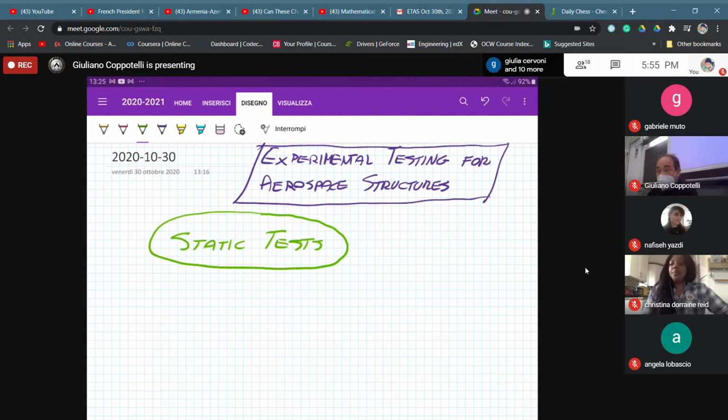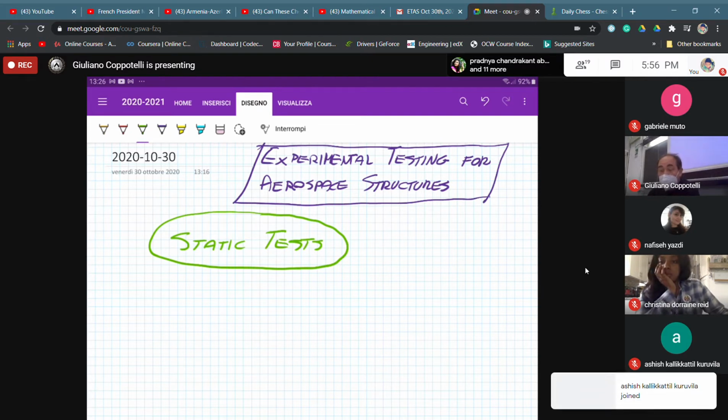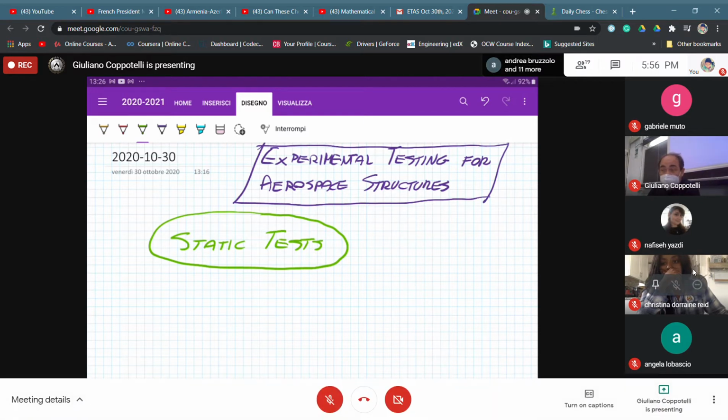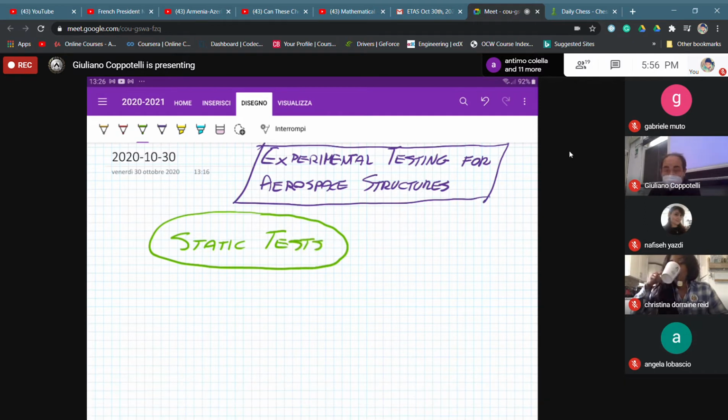Why? Because without doing any other additional test, you can predict what could be the effect of a prescribed load, for example, a maneuver, a flight path or whatever. Or you can also predict the effect of some structural modifications in your structure without doing any other test. So you have the power to cut out a lot of costs in the development phase and in the certification, because you prove that your finite element model, or your numerical model in general, is good enough to represent the elastic behavior of your structure. And that is the point.